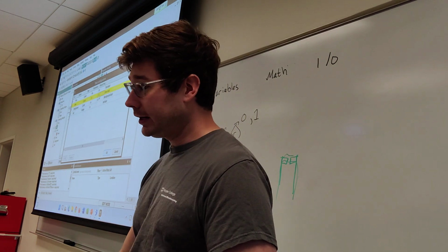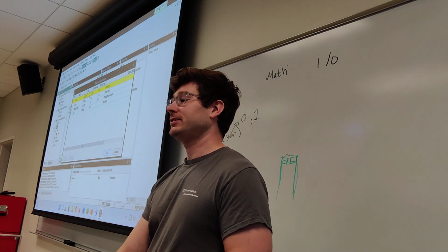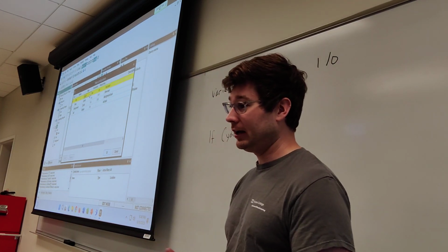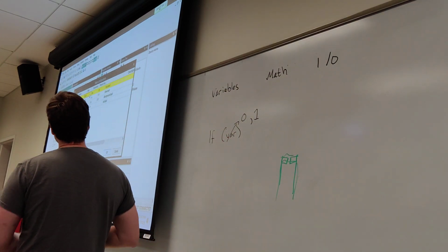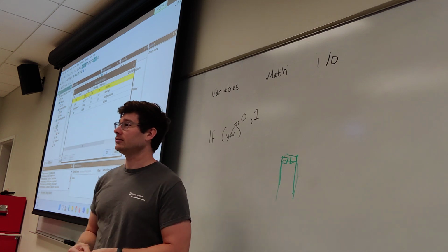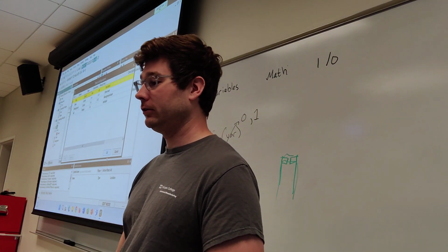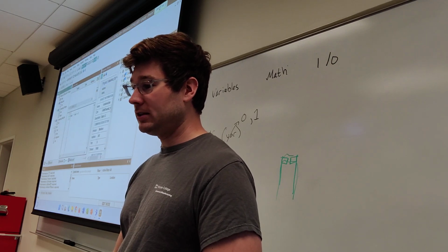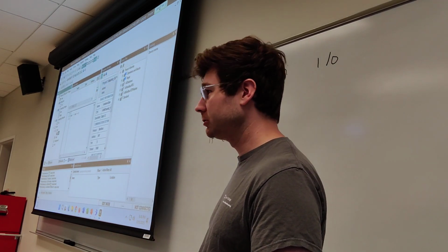And then we have slow tasks, which take 1/10 of a second only. And then fast tasks, which take 10 milliseconds. Okay, we can essentially do anything that we put in this fast task group 100 times a second, right? Every 10 milliseconds, we'll be doing that task, okay? Notice that by default, our main program is inside of the fast task group.